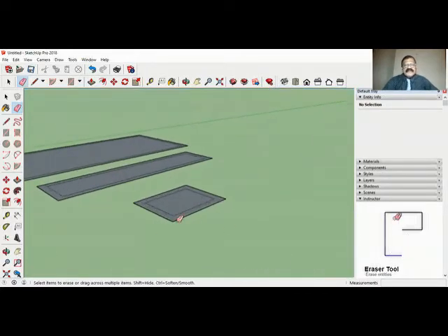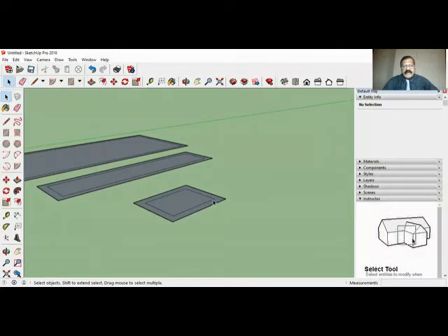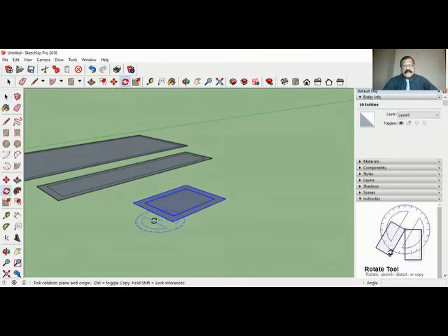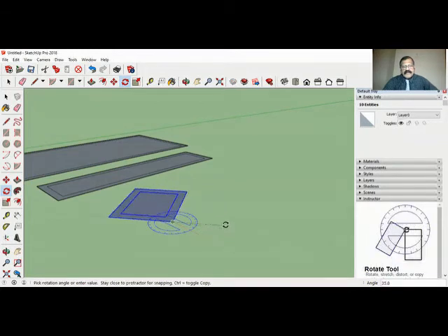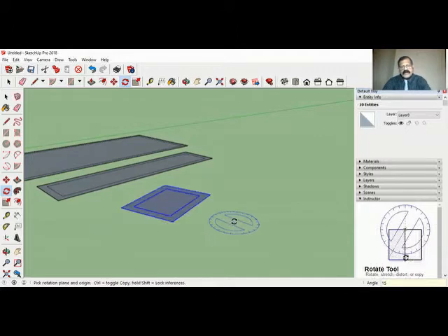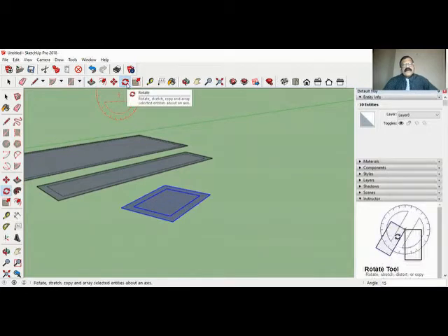Suppose I want to rotate this. What I will do is first I will select. So for selection, object, you can show window or just 3 times double click. 3 times you have click. The full object is selected. Rotate. You see here, keep it this corner, draw a line parallel to red, click, now rotate. Whatever angle you want, you give the value. I want to rotate 15 degree, so 15. So it rotated from the main 15 degree. So that is for rotation command.